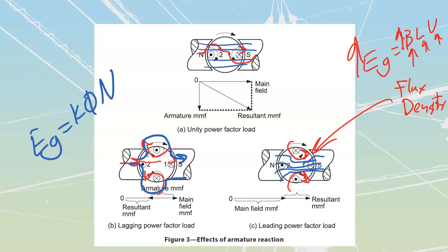Is my voltage on my genset high? That's weird. My voltage usually should be lower, therefore I'm probably looking at that something's been added. That's going to be a leading power factor. Same with if my voltage is really, really low, do I have a lagging power factor? You can do some checks. We're going to learn in PQA about how we can use things like crest factor to check for things like harmonics, etc.